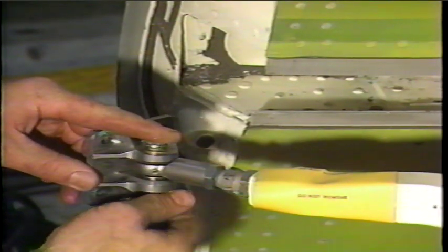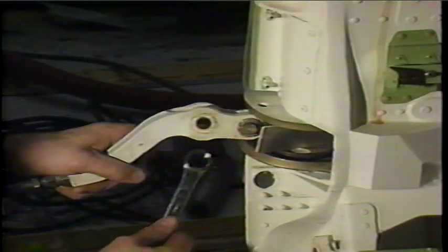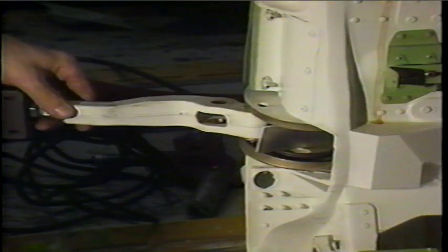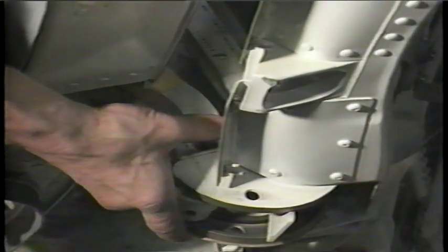Bolt the support bracket to the guide arm and tighten the nut per the maintenance manual. The guide arm cam follower pin with the spacer over each end is inserted into the cam plate tracks. The guide arm is moved by hand until the lower hinge link lug fits into the slot in the guide arm. Then the elbow pin is inserted and the securing spring installed.